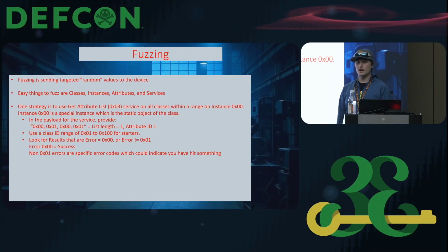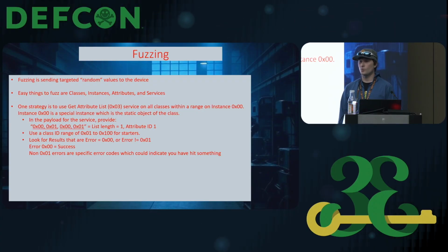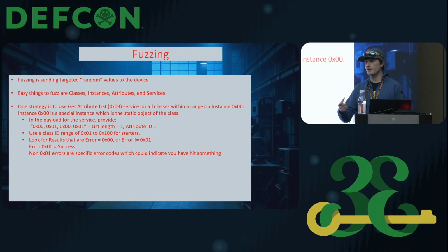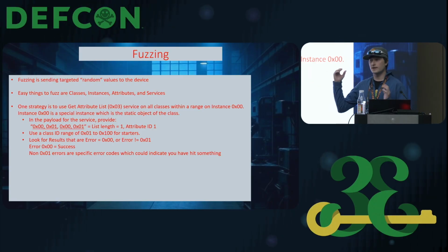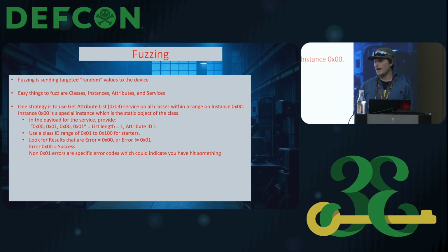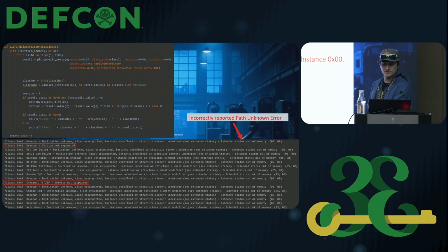And that's a really common way to find out what C++ objects in my firmware are attached to the CIP protocol within that device. That gives me very quick and dirty knowledge of what actually is in the device. How do I find what functions I have available to me? Because there's no way to say, hey, tell me what you can do. The vendors don't want it to have that function, right? So it's not going to give you a list of everything it supports. You have to go find it. So fuzzing is a really cool technique to do this.